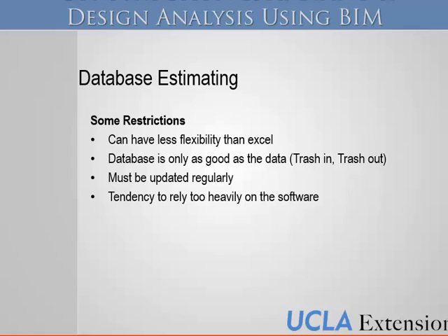Environmental issues, like California. We have the same foundation here in Ohio, of course, here it is more expensive because of earthquakes. Totally, it depends on the location of the project. Yeah, and every project is so different depending on the soils report, right? If there's a note in the soils report that you have to over-excavate 10 feet under your building pad and recompact up 10 feet, then it's going to be a very different number than if you figured you could just go right on grade.